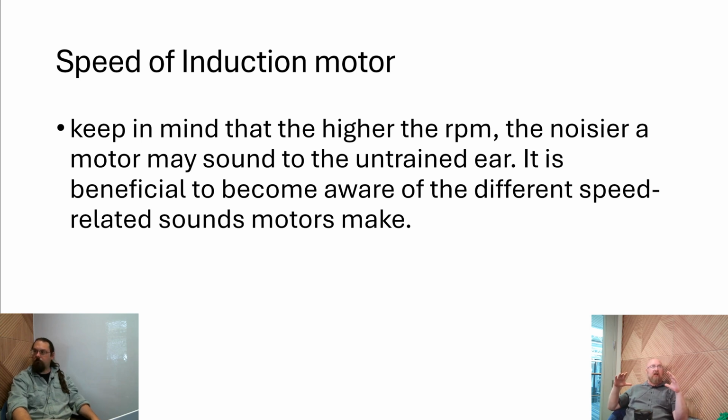There's a lot more wobble in the velocity naturally, because at some point it's farther away from the thing it's attracted to or repelled from. So there's more vibration and wobble in lower pole motors, which may become critical in certain applications. It's also part of the reason why these pole configurations have different auditory signatures.